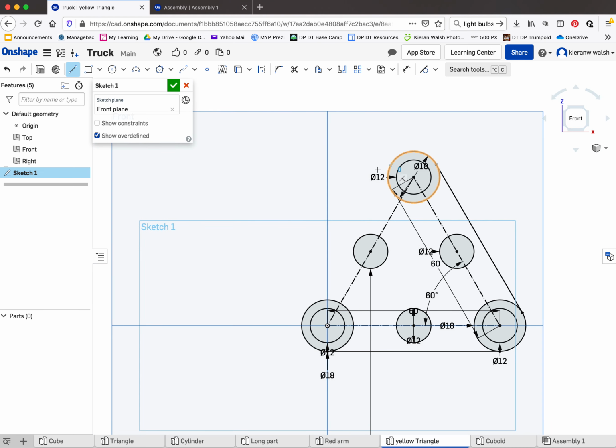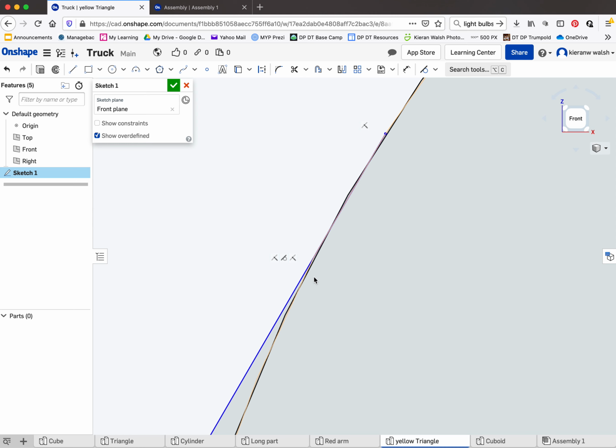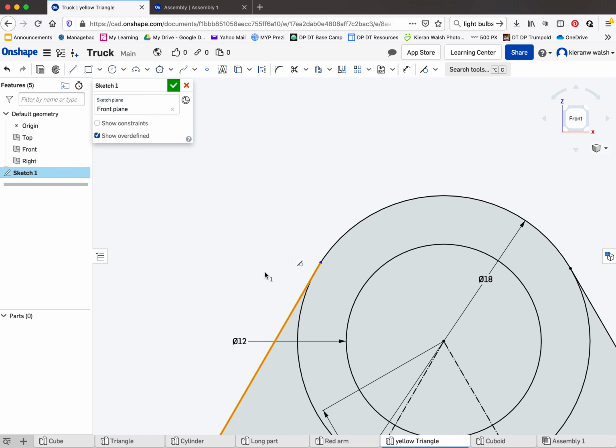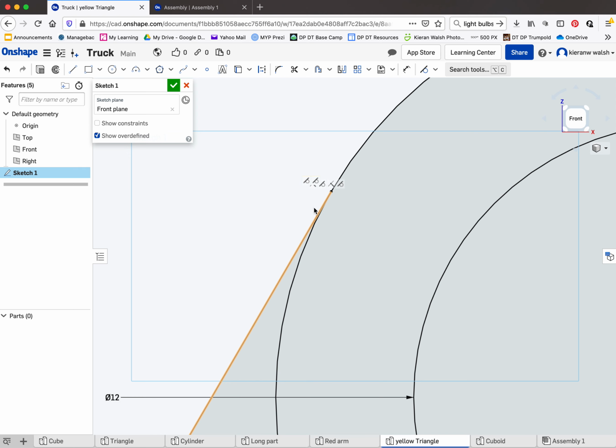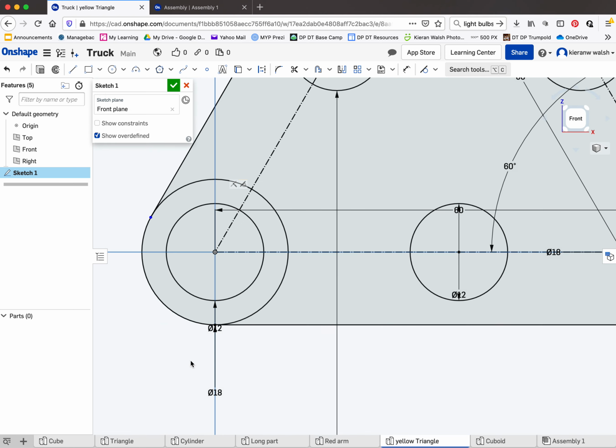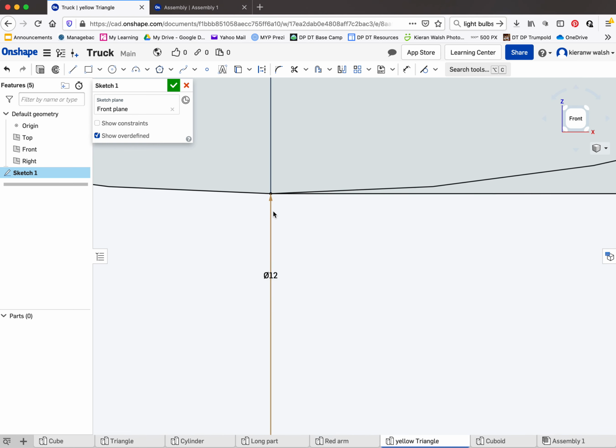Yeah. Jumped away from the circle there, so this time use this tool again. So we're going to hold down the shift key, select that line, and just to show you where it is, tangent, and it will find it for you. Go up here, that looks okay, but I'm just going to do it anyway. I'm going to select that line, and again, tangential. Yeah, moved it a little bit there, so it wasn't quite correct. You can even do that with these down here if you want to be perfect, but I think they should be okay. Yeah.